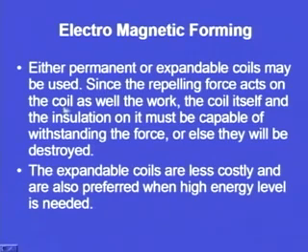Since the repelling force acts on the coil as well as the work, the coil itself and the insulation on it must be capable of withstanding the force. So it should not happen that the coil gets damaged or fails. If it does not have the required strength, there are chances that the coil may fail. The expandable coils are less costly and are also preferred when high energy levels are needed. So when we need a very high energy level, in those particular cases we may go for expandable coils, which may get destroyed during the operation.